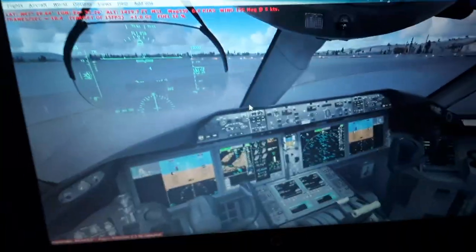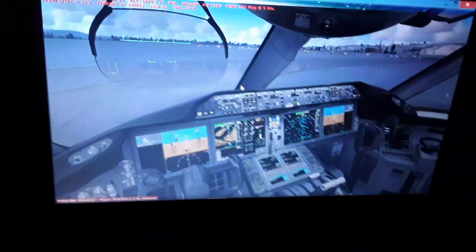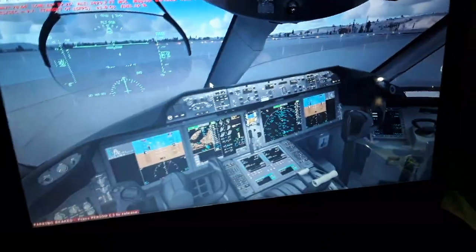we have the VOR stations, ADF and the NDBs, which are navigation aids, the navaids. Also we have the waypoints which are horizontal and vertical navigation fixes with altitude and airspeed constraints. The aircraft is going to have to fly through some waypoints during its flight. So you will see we're going to select using the flight management computer over here, and it's going to be displayed in the navigation display and also in the HSI when we create the flight plan of the aircraft for this flight or any flight. So also you're going to see other systems, the outside view, the flight controls.